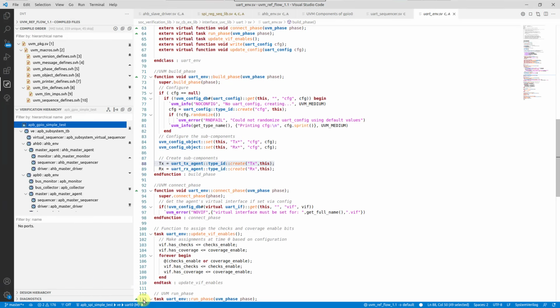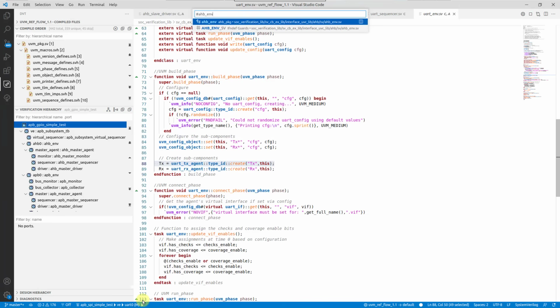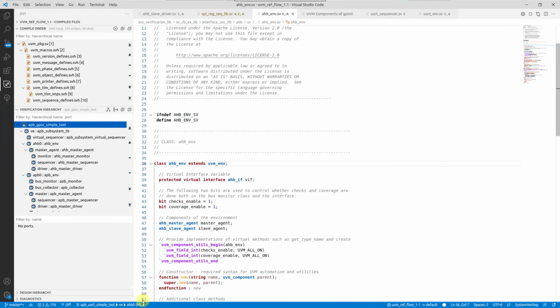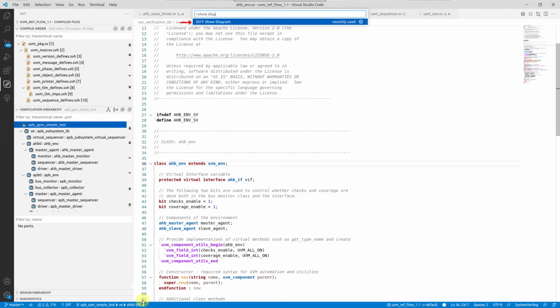The Unified Modeling Language, or UML, was devised in the software world to provide a standard way for visualizing classes along with their members, as well as relationship among classes such as inheritance and associations. To see the UML diagram of a class, simply place the editor cursor on its name and trigger the Show Diagram command. Then choose UML Diagram.